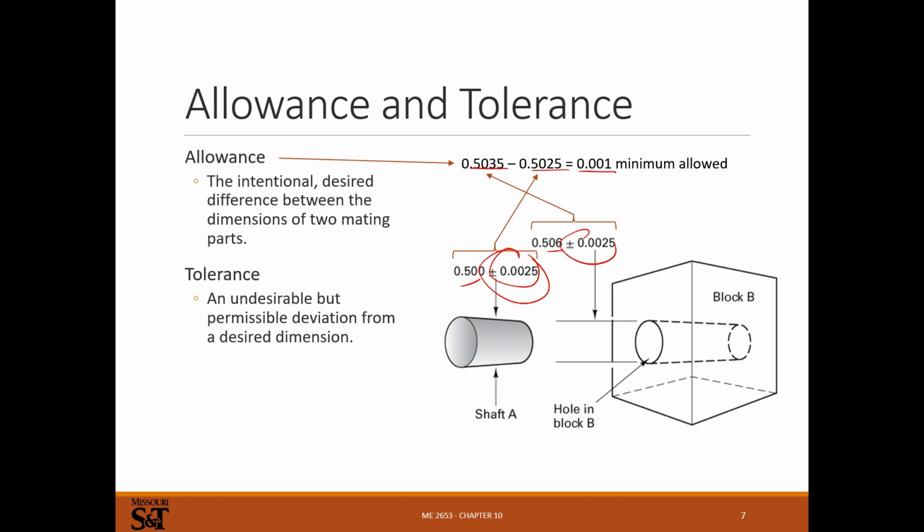You can sit there with the same setup in a CNC machine and make 100 parts, and they're all going to vary slightly in their dimension. It's going to look mostly like a normal distribution, but even in a very controlled process, there's going to be variability. There's just so many stacked up different things that can change in any process. There's always going to be a little bit of variation, and you have to establish what's allowable and what's not, and then you have to put these two things together to determine if a fit's going to be correct or not.